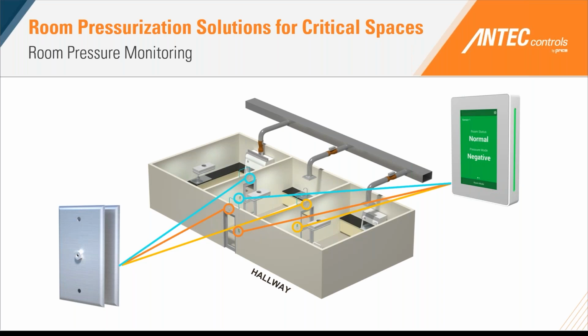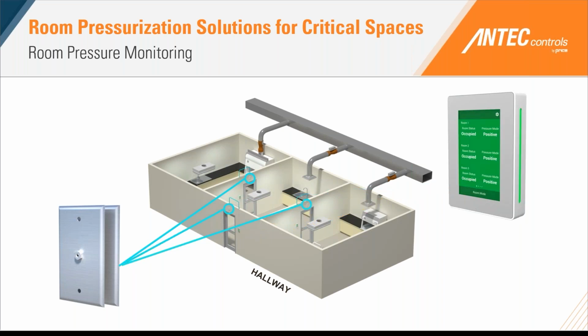Another strategy you can look at is potentially minimizing how many pressure monitoring displays you have. So in this sense, we have 3 pressure transducers, but instead we're going to have 1 pressure monitor, and that 1 pressure monitor is going to reference all 3 pressure zones for us. So instead, we now have essentially 1 place to go to see that pressure reading for all spaces.